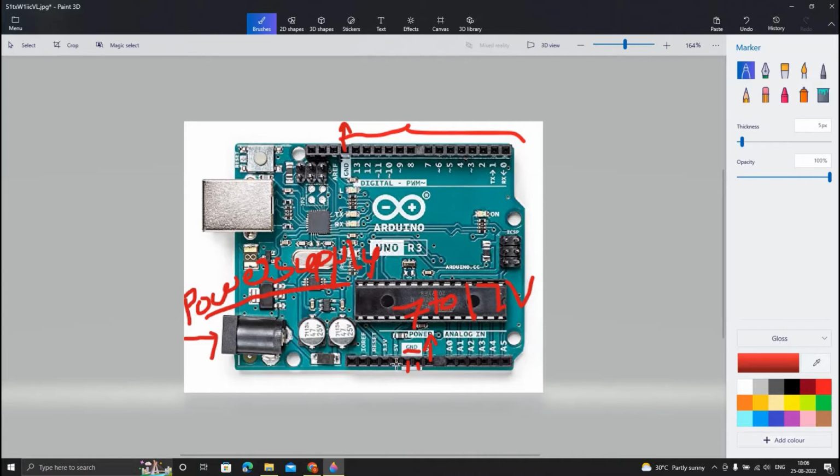After that we can observe the 5V pin, input output also. We can give input supply to the board, or you can also get an output from this board while connecting through the power supply, and also from the USB B type port. We can also see a 3.3V pin, one reset pin and one input output reference pin.